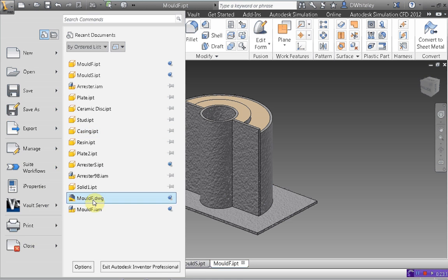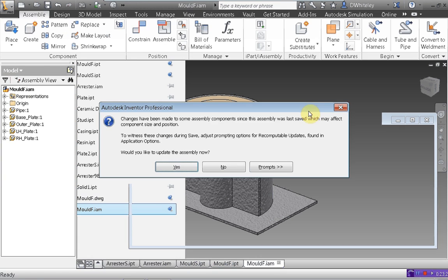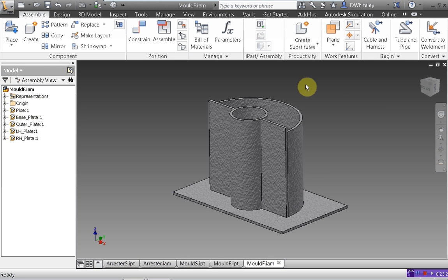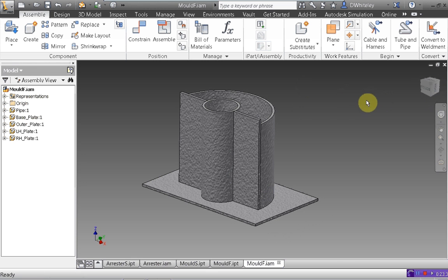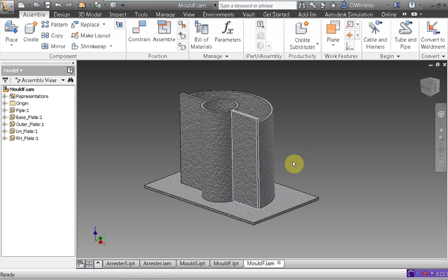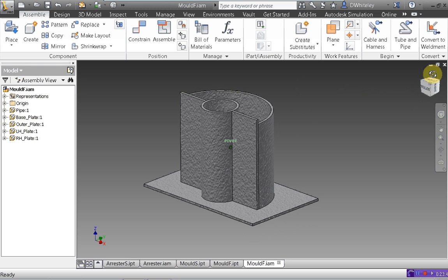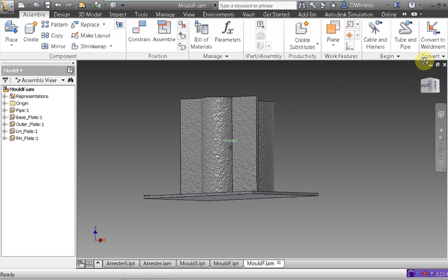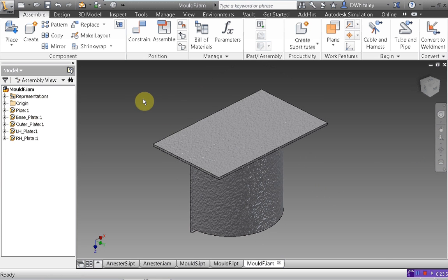Now, a word of warning here, because we're working on a single part initially, the multi-body part, I can bring the properties across, but things like length, width and thickness aren't really much use to me, because I was working on a single part, and all these components might have different thicknesses and they will have different lengths and widths. So if you wanted to put cutting lists out for your parts list, your bill of materials and parts list, it is important to actually get the information on the parts as they arrive in the assembly. Don't do all the work in the part file.